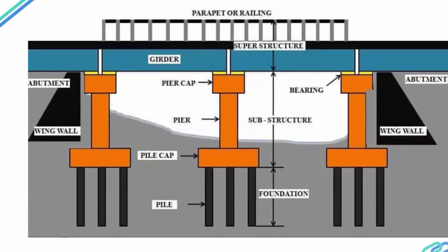For example, in girder, we have various options. We have a U girder which can be used. We have a box girder. Then in box girder also we have the option of going with the precast part or the cast in situ part, pre-stressed part or reinforced part, whether to make it pre-stressed or to make it reinforced. Then again, we need to decide whether we need to go with an open web structure like a U girder, or a box girder, or an I girder, or a steel girder, or we need to adopt a balanced cantilever construction using a box girder. So there are a lot of